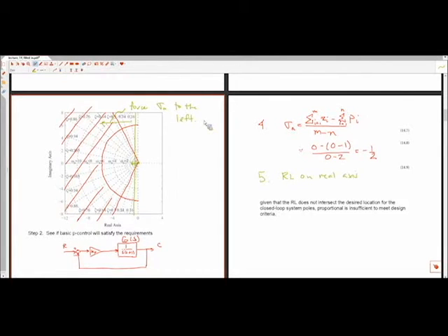Okay. And so if we look at how sigma A is determined, it's determined by this equation. Since we only have poles in here, the intercept is just essentially the mean of all the poles. When we have poles and zeros, it's no longer the mean of them because zeros add and poles subtract.